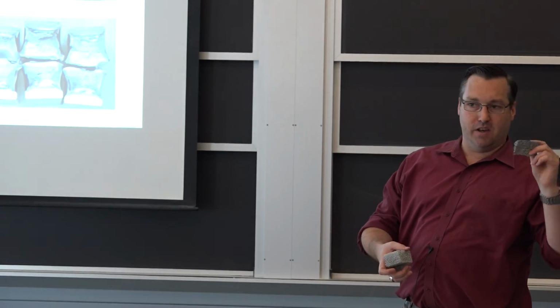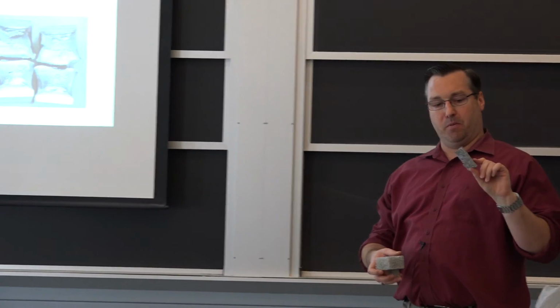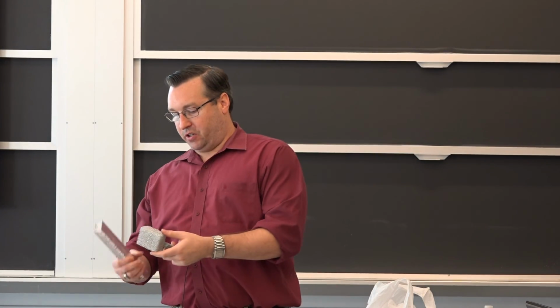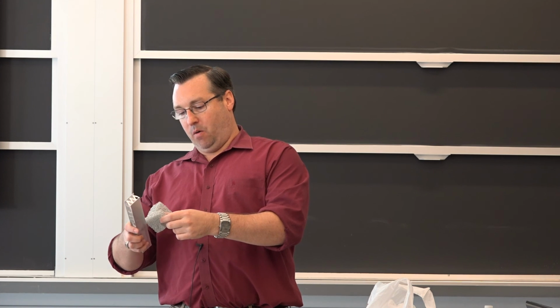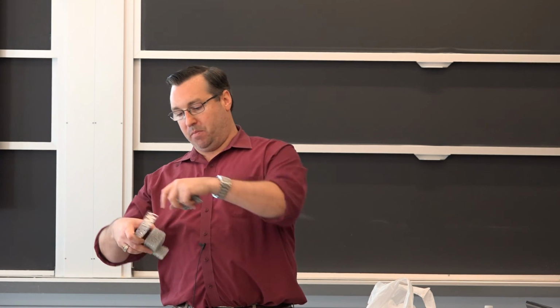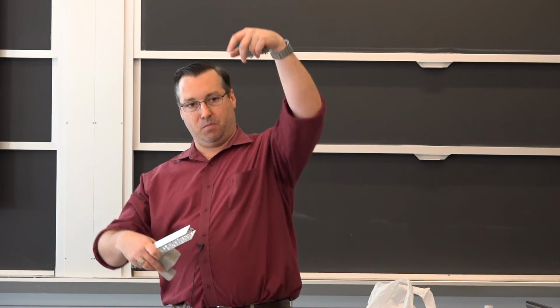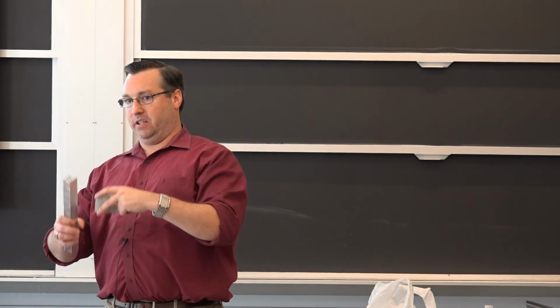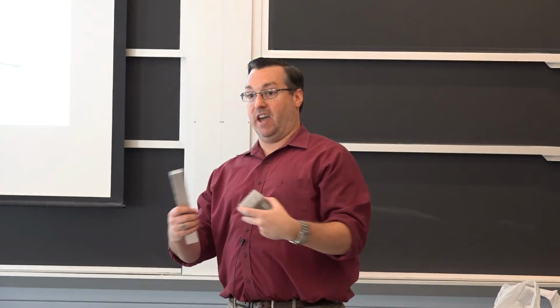You saw this. This is what's called a closed cell aluminum foam. This is open cell. So what we were looking at was doing what's called a dip brazing procedure, where you put it together and dip it in a molten bath of sodium fluoride, take it out, clean it off, and then it's all joined together.